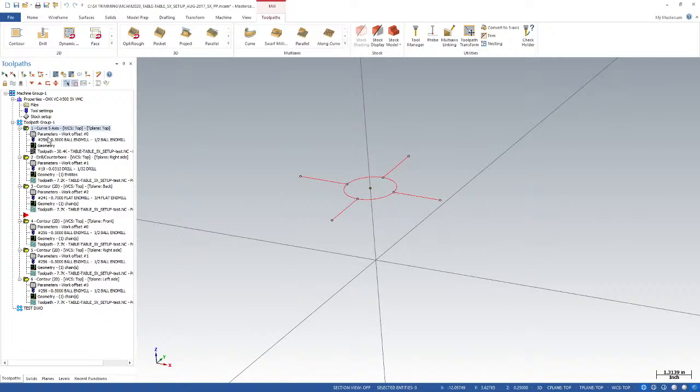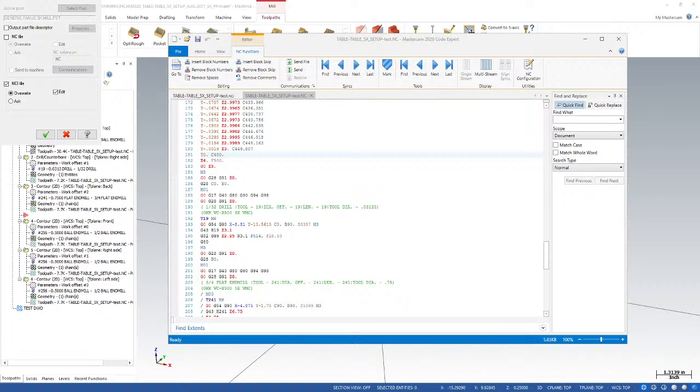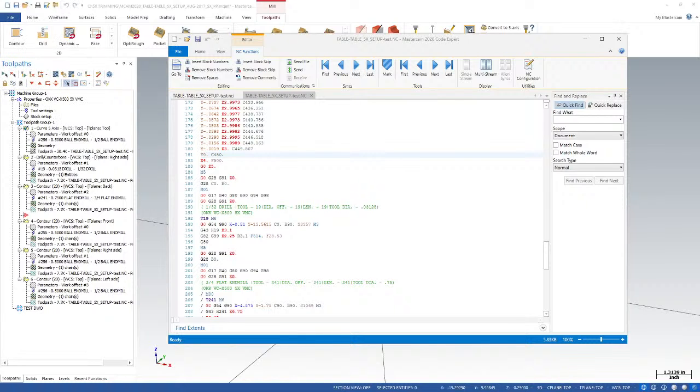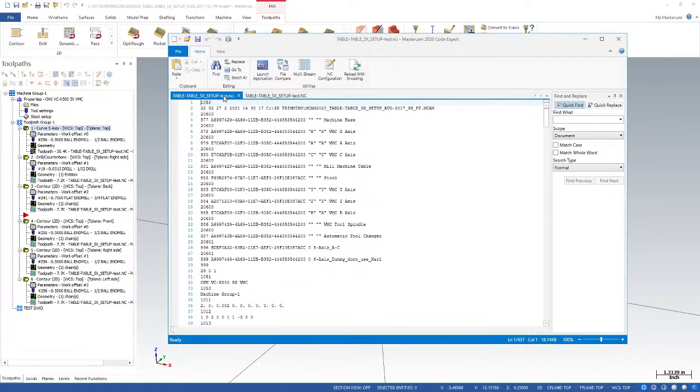With this toolpath here, rather than it being 3-axis code, before we look at the actual path itself, we'll get to that, let's look at what the output for the post processor looks like. So I'm going to post out the NCI file, and we'll say NCI overwrite edit, and I'm just going to post out this 5-axis path. But I'm posting out the NCI.